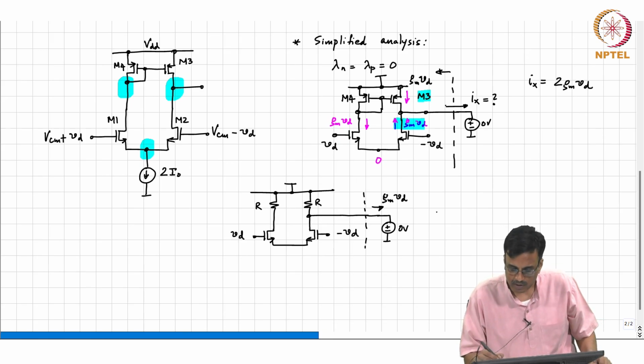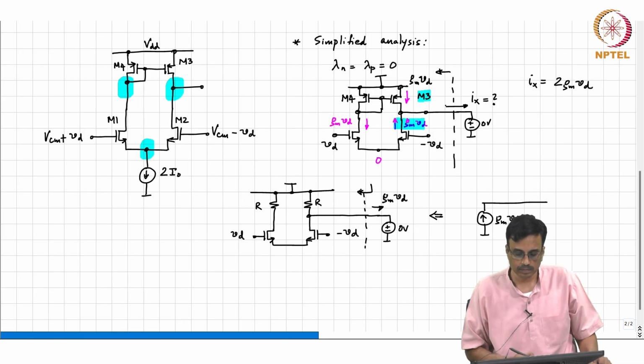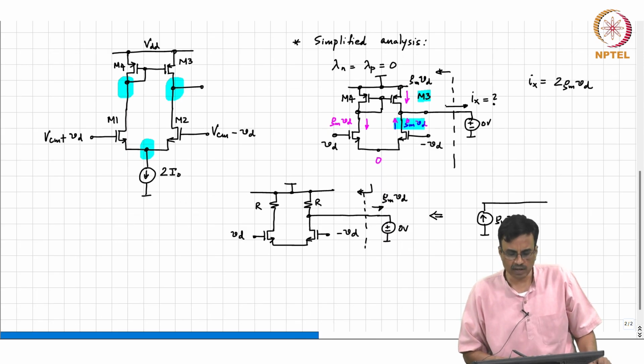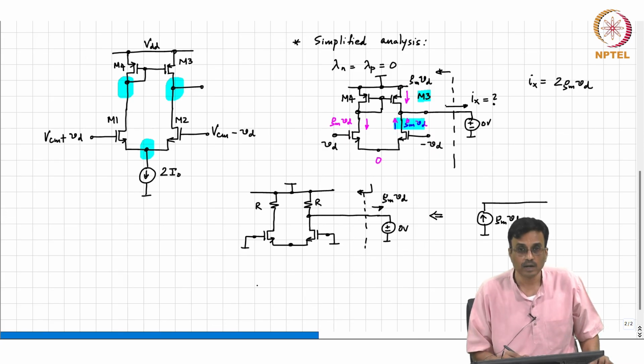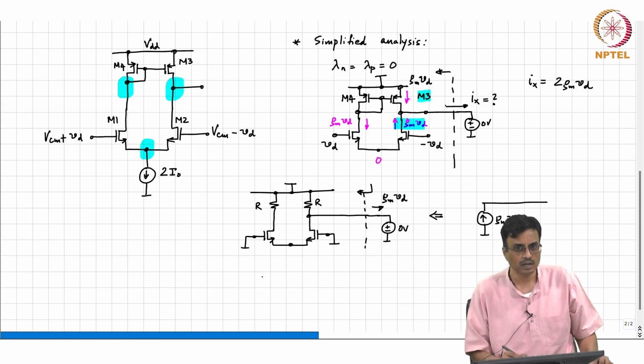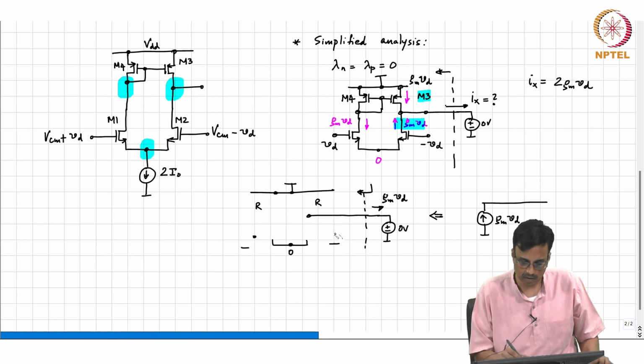So, let us go back to the earlier one. The short circuit current, as you can see, is GM times Vd. We already saw this before, but I want to see it in another way. What is the Norton resistance looking in here? To find the Norton resistance looking in there, what would we do? Deactivate the sources. So, that is Vd goes to 0, this Vd also goes to 0. What is this incremental voltage? 0. So, what happens to the two transistors? They are just not there.